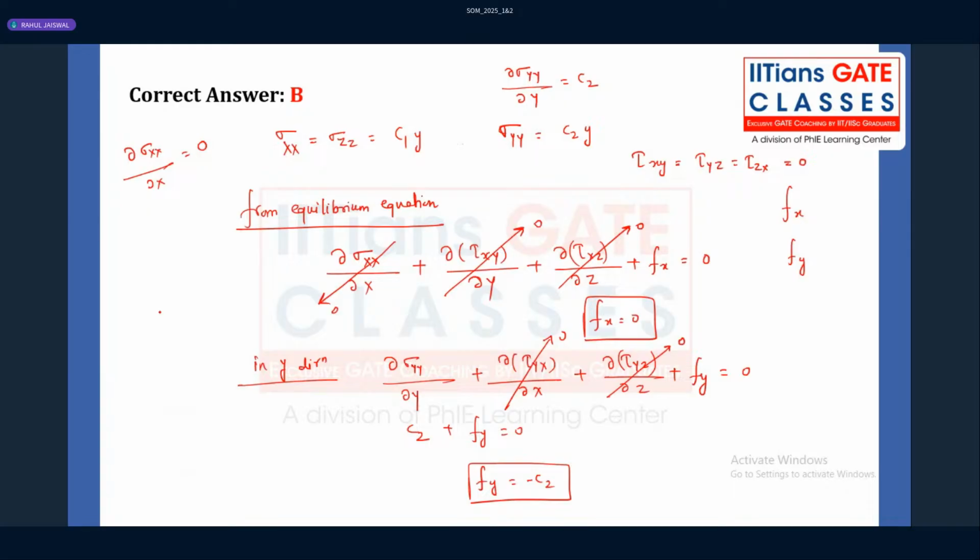For that uniformly varying load, where there is more load, it has to be resisted maximum by the left support, because in the left portion there is the maximum intensity of the load. So definitely Ra will be more than Rb, but still for confirmation and purity purposes we need to solve it. But for saving time, in a quick time you can answer it.